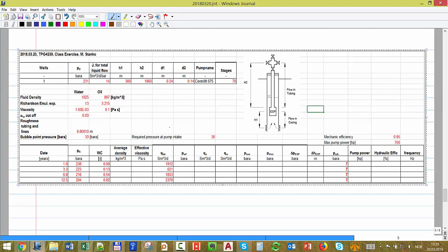The pressure upstream of the pump and the pressure downstream of the pump. Be aware that they might not be in exactly the same place; you might have some distance in between. The suction might be much lower, the discharge might be much higher, but what matters is the difference in pressure between the two. Let's see if we have that information here.